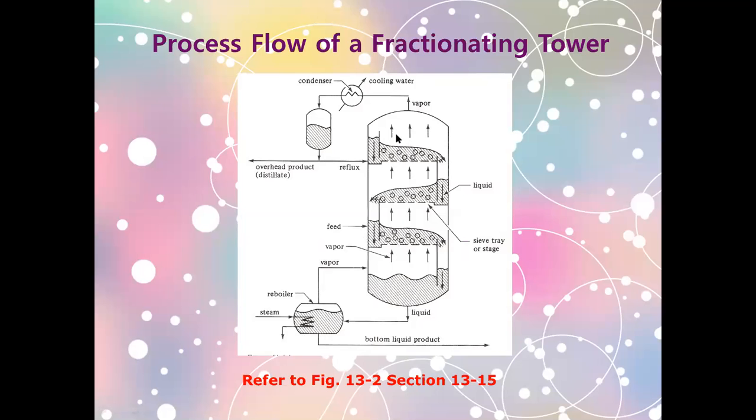Now, initially, we don't have that, as I have mentioned. Now, the rest of the liquid that was not turned into vapor is withdrawn as bottoms liquid. Now, for the vapor that goes up, you have this vapor introduced into our condenser. The purpose is turning it into a liquid. Part of that liquid is returned into the column in the form of reflux. The rest, the major portion, is withdrawn as your final product. So this is how a very simple distilling column works. That is the column which has a reflux liquid.